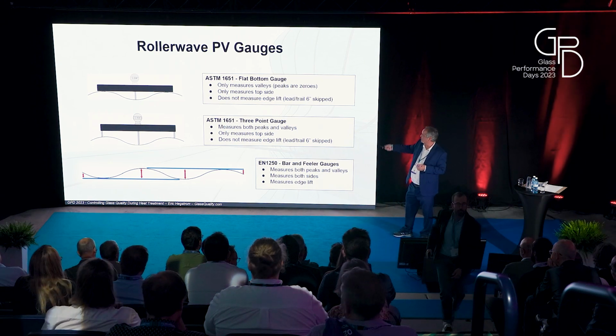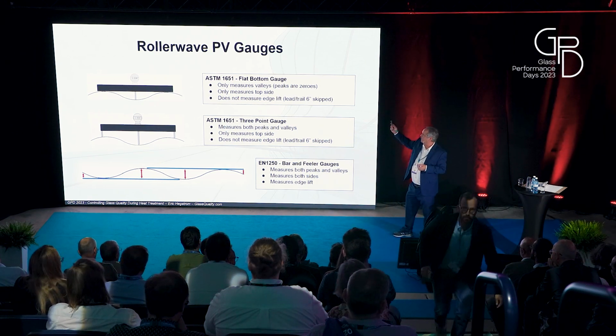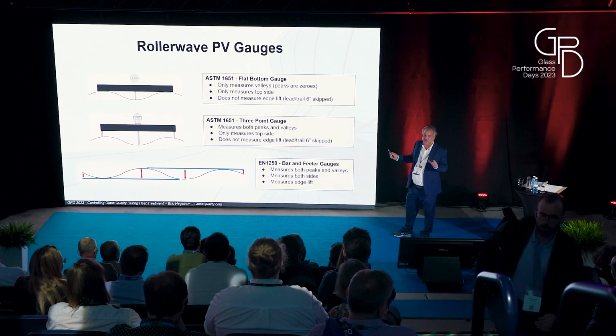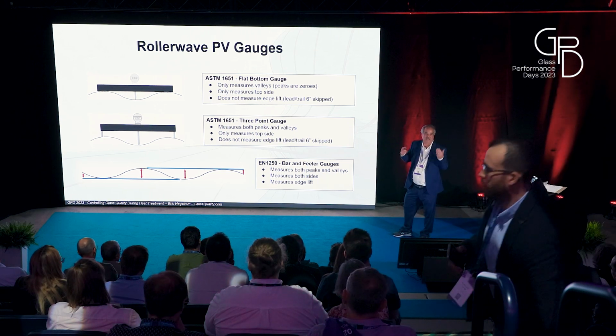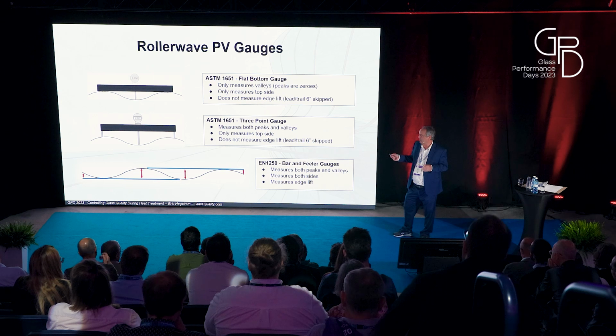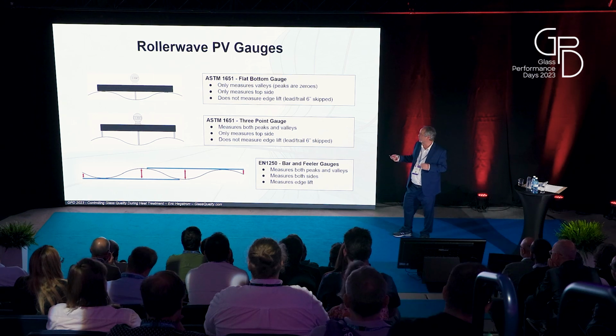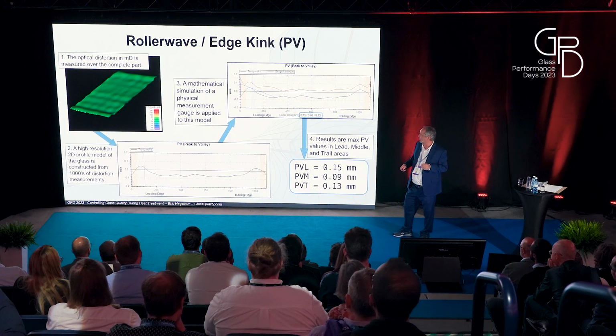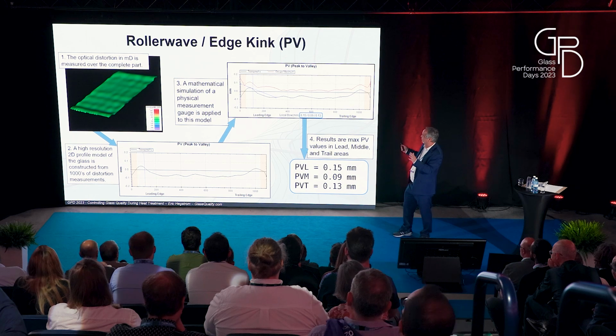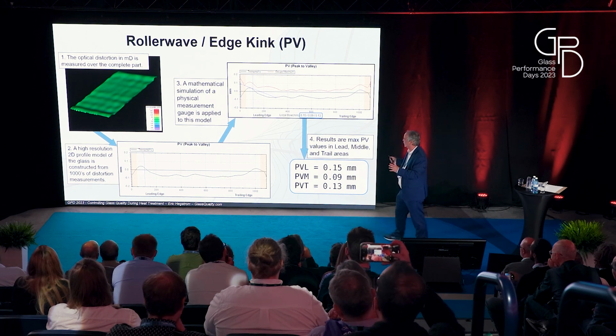But it's just important to understand that what peak to valley number you're going to get from the same piece of glass depends on what type of gauge you are using. And that's something that I think a lot of people don't get until they start playing around with it. That is a kind of a complex slide here, but man, that is a beautiful monitor.